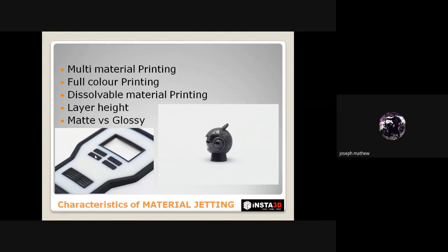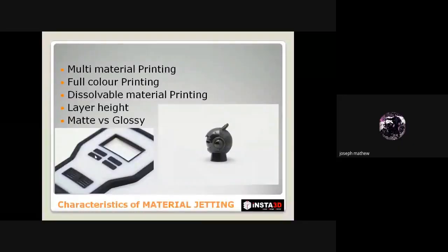Basically, PolyJet uses 2 materials. One is Vero and the other one is Tango. The Tango material is flexible, and the Vero material is a bit hard and tough in nature. So by mixing these 2 materials using the nozzles in the printing head, the final component can be obtained where the single component has both the strong material as well as the flexible material.